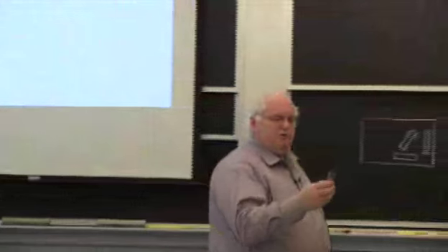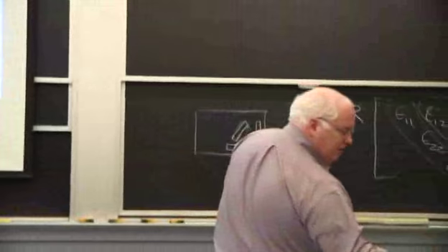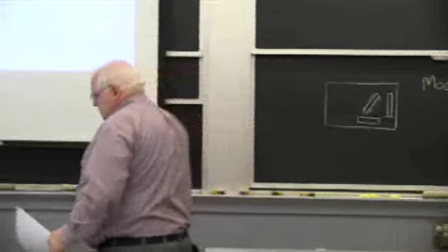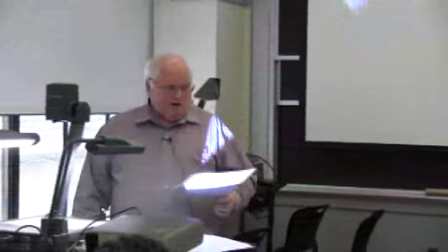This is a cup and cone fracture. I don't even remember what it came from. I think it might have been from some testing we did on a gas well in Louisiana. But anyway, that's a cup and cone fracture, which is a typical neck down fracture. This is what a cup cone fracture looks like.